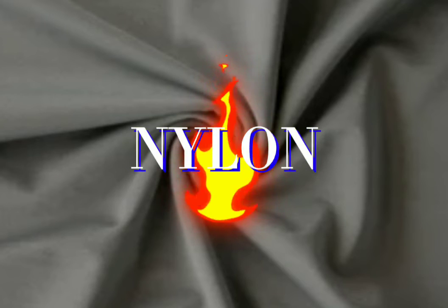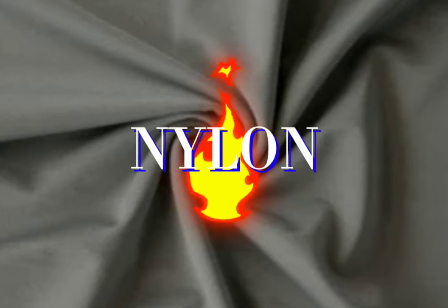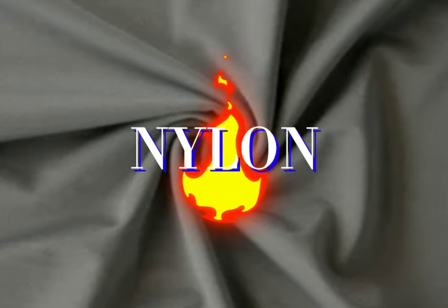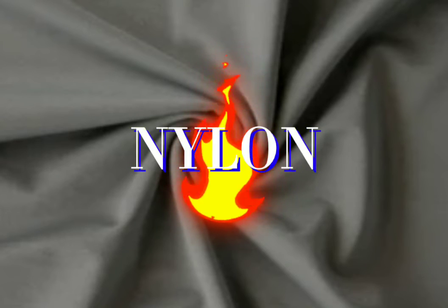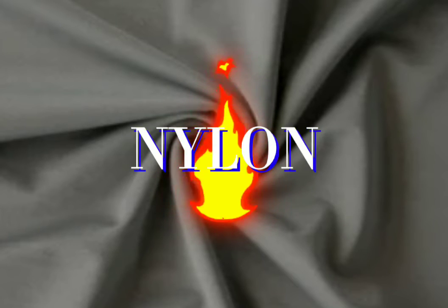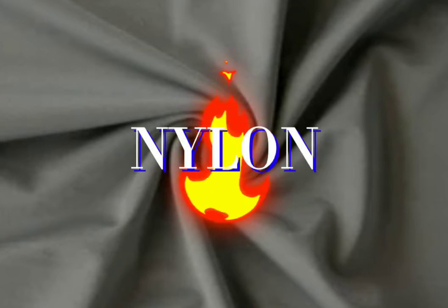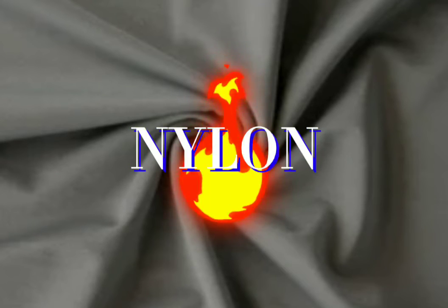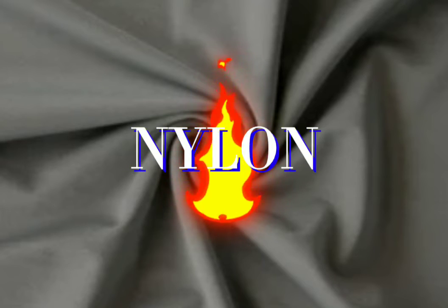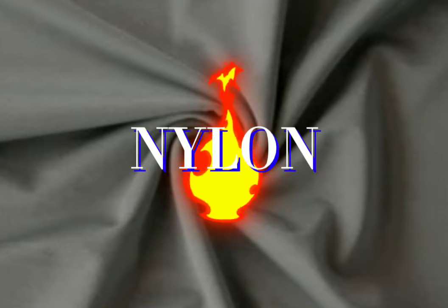Nylon is classified as a thermoplastic, as opposed to a thermoset material, which refers to the way the plastic responds to heat. Thermoplastic materials become liquid at their melting point, a very high 220 degrees Celsius in the case of nylon. One of the useful attributes of thermoplastics is that they can be heated to their melting point, cooled, or reheated again without significant degradation. Instead of burning, thermoplastics like nylon liquefy, which allows them to be easily injection molded and then subsequently recycled.